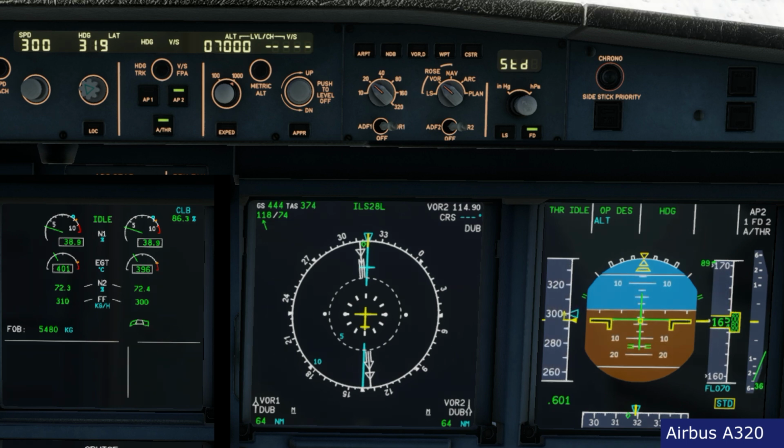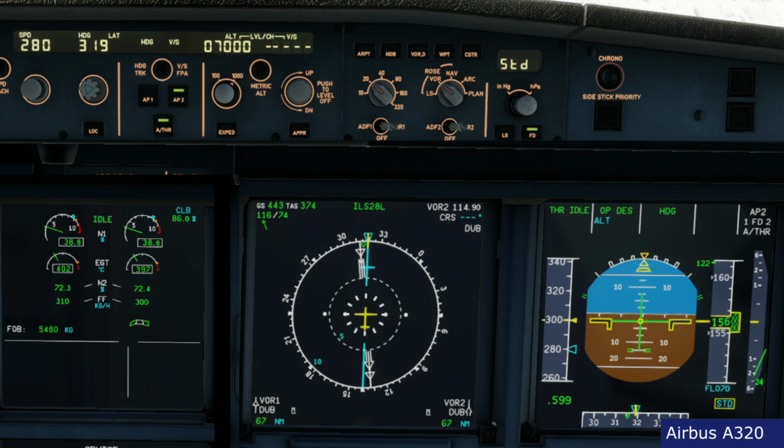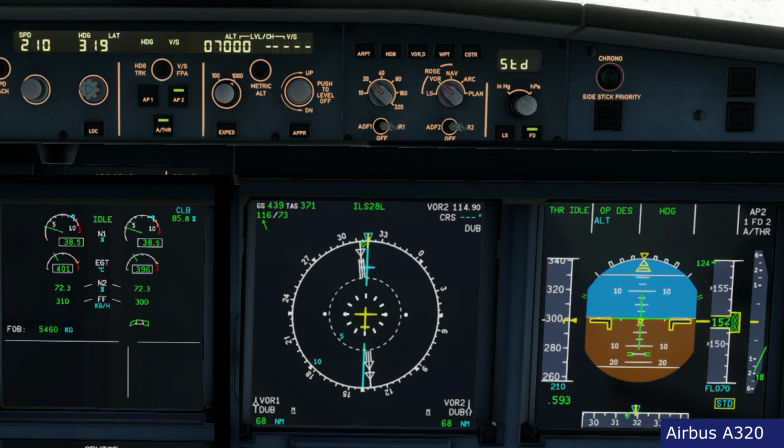And as we reach the selected speed, what will happen, of course, is that we reduce the rate of descent, because we just want to maintain the speed, we don't want to accelerate anymore. Of course, the very same way, if I elect to fly a lower speed, the aircraft will start pitching up in order to reduce the speed, and therefore we lose less altitude, we lose less potential energy in order to waste the kinetic energy and have the speed reducing.